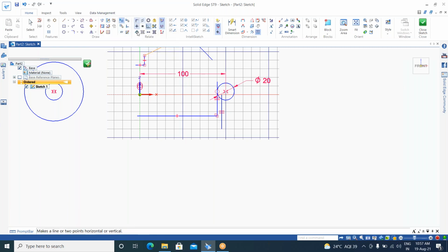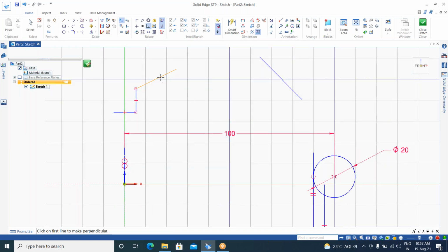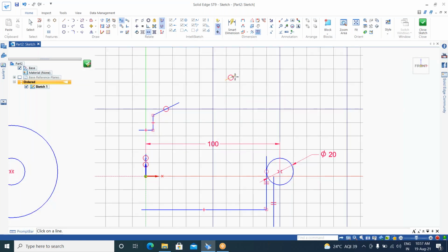In the next drawings you will be able to understand what over constraints are. I will continue with the remaining one, collinear. Collinear is, for example, two different lines. I'm going to make these two lines collinear, so I change the inclination of the line with respect to the inclined reference line. See, it is completely aligned, completely collinear with the reference line.